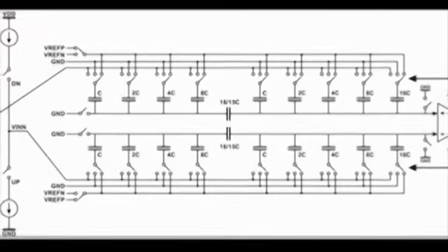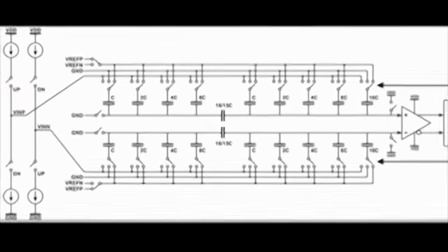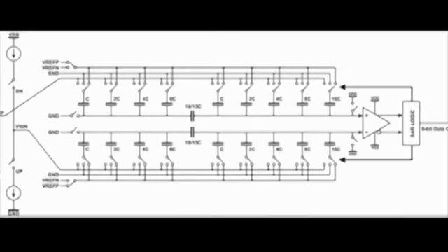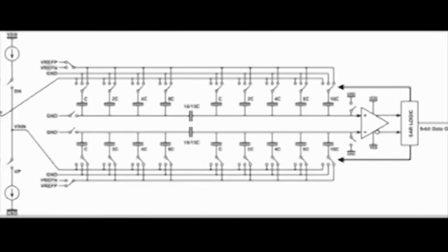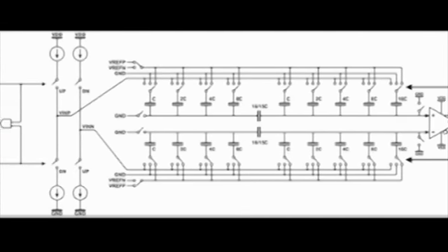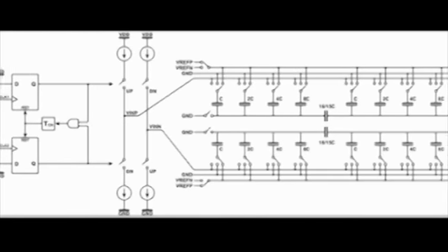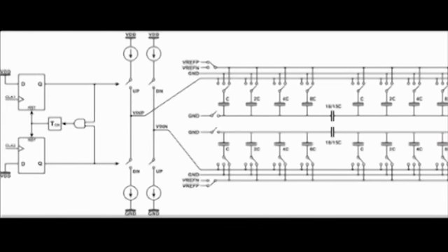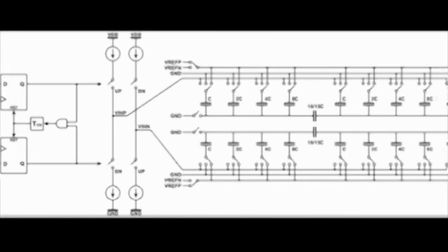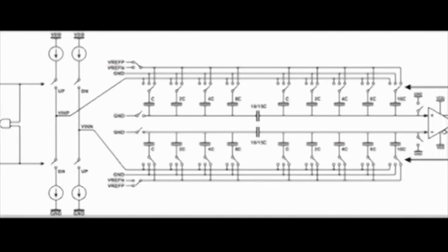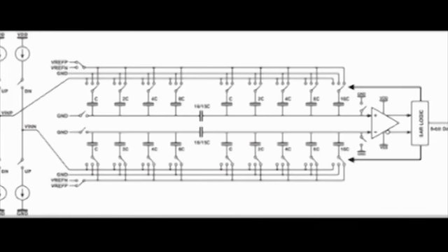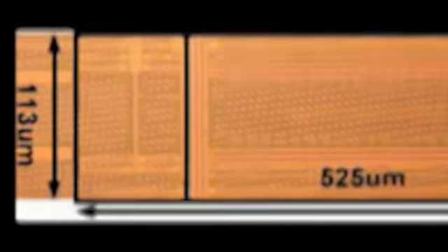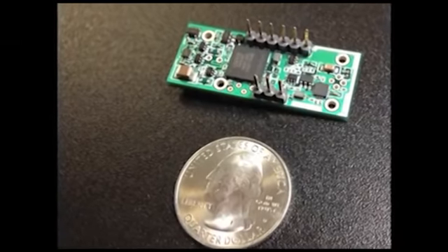Here we propose a design for a time digital converter, an IC that can tell the time difference between two events as a digital signal. The time digital converter works by receiving two electrical impulses as inputs. Then the system will convert the time difference between the two inputs to 10 bits of digital signals with a resolution of 1 picosecond. With a size less than 1 mm square, our time digital converter design could be integrated in any chip easily.